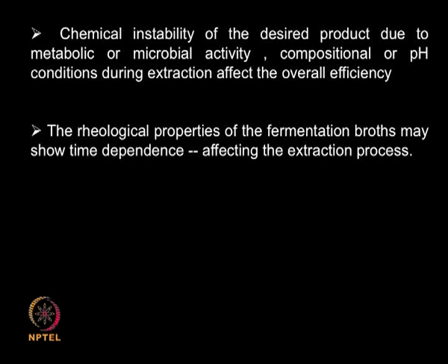Then the rheological properties also are getting disturbed. If you take a fermentation broth and if it contains cell mass, dead cell debris and so on, it will be highly viscous, and we need to now mix your solvent with such a highly viscous fermentation broth. So the rheological properties will have a bearing on the extraction process. So you need to keep those points also in your mind.